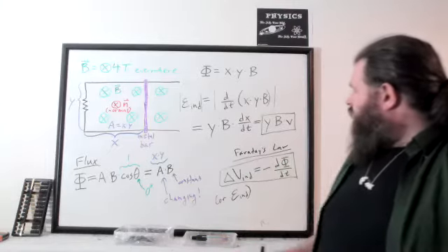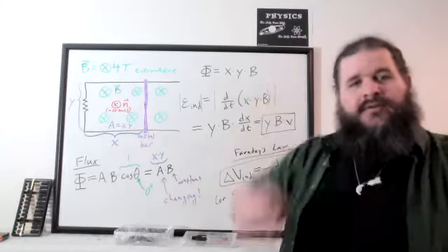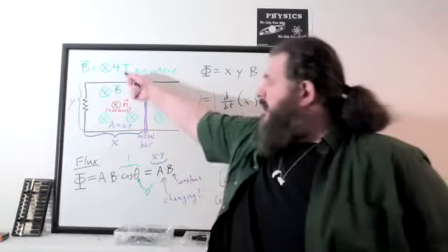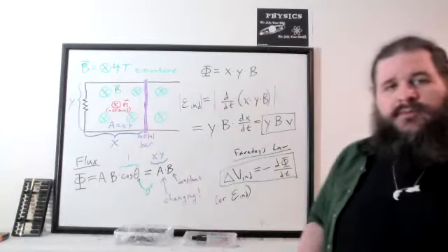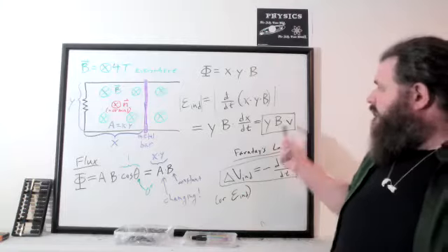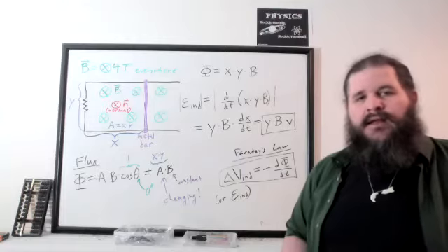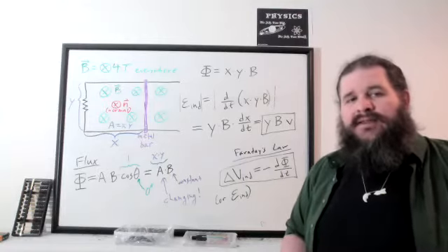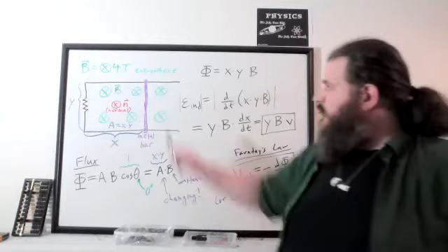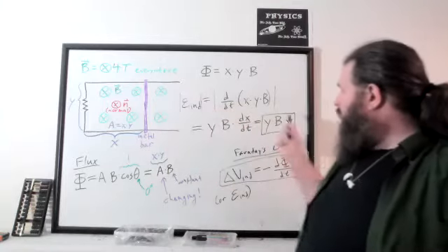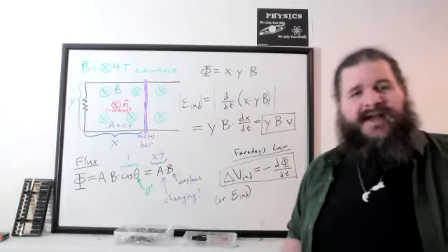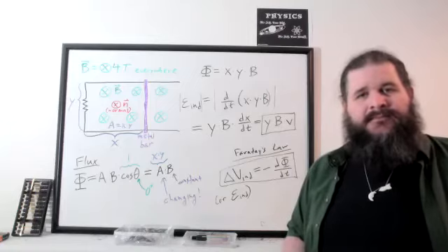And so this suggests that the further apart the wires are, the more voltage we get. The stronger the magnetic field is, of course, the more voltage we get. And also, the faster we're pulling this bar along the track, the more voltage we get. But note that this only applies while we're in the process of moving the bar. As soon as you bring the bar to a complete stop, v is 0, so the extra voltage vanishes and you don't get any current flow.